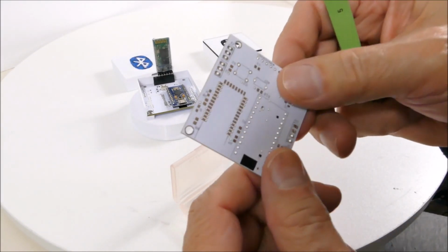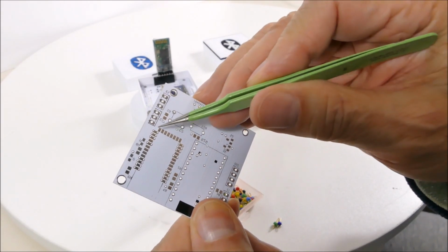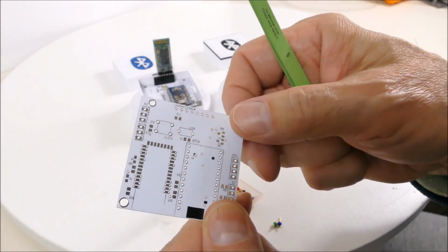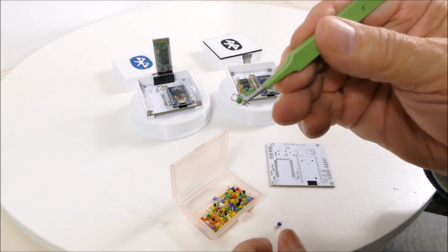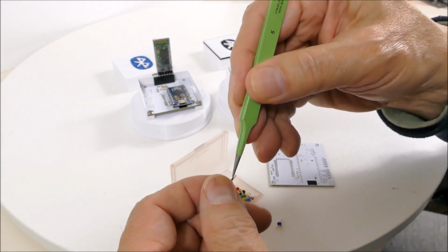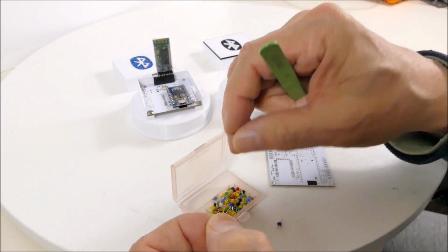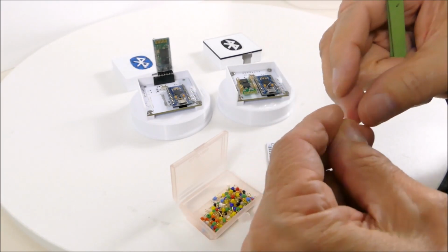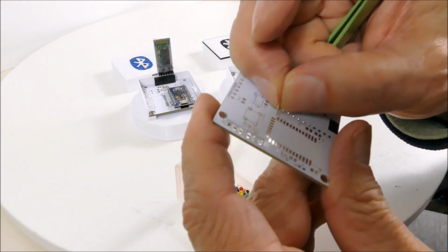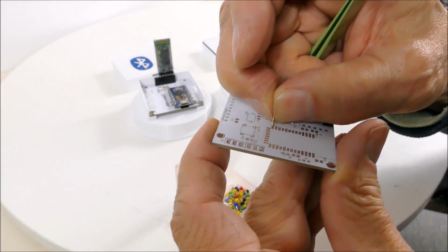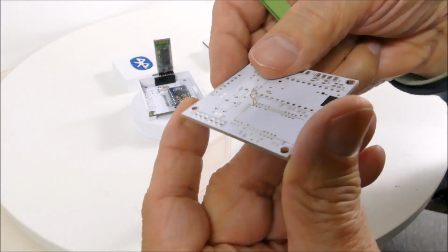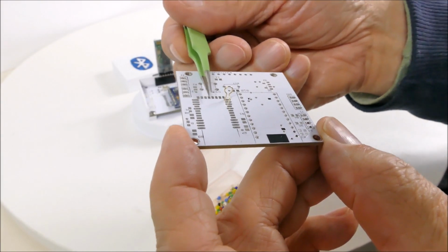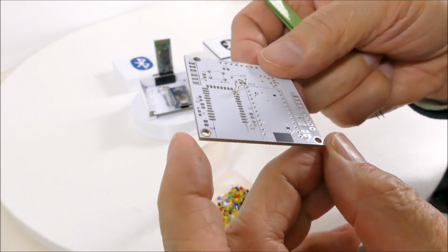So the way that works is on the circuit board, I don't know if we can see this, but the pads here have two holes, two vias for each pad, which allows me to put in these test points. So the little test point has a little hoop, and these little beads can be removed, leaving just a little hoop with two pins, and that gets inserted into these pads that have two holes like this. And I just solder one of the pins, and it allows the rest of it to be spring loaded so that it makes good contact with the notches in